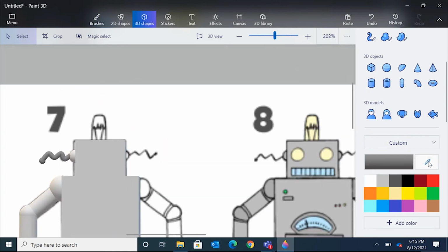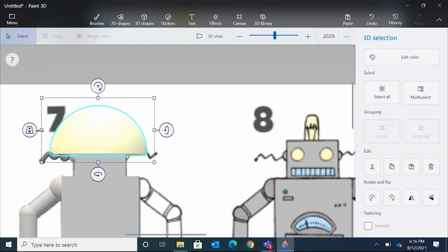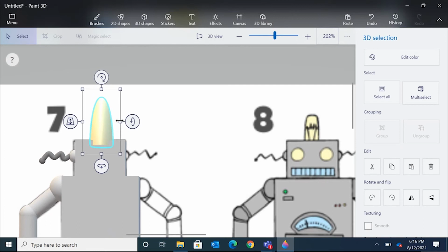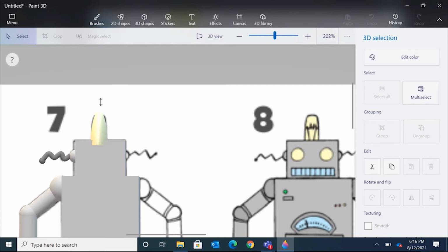You can also create some of these lights. So I'm going to select this color of the light. There's probably a couple different ways that you could do this here. You could probably grab the hemisphere. I'm going to click here. And then I'm actually going to grab the sides, which is something we haven't done before, right? We've normally just grabbed the corner, so we're going to grab a side. Maybe shorten up this side a little bit more, and then push down the top. So that's one way to do it.